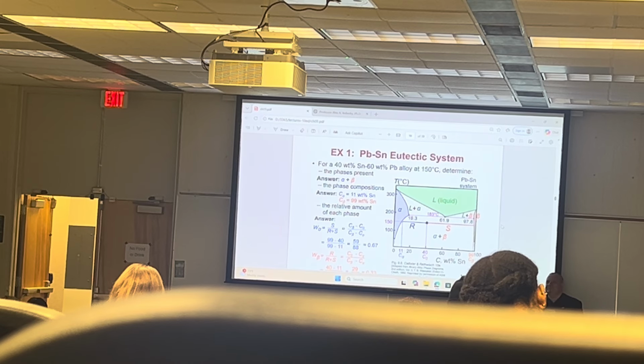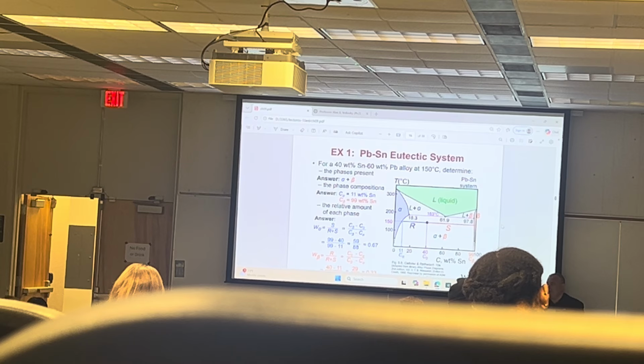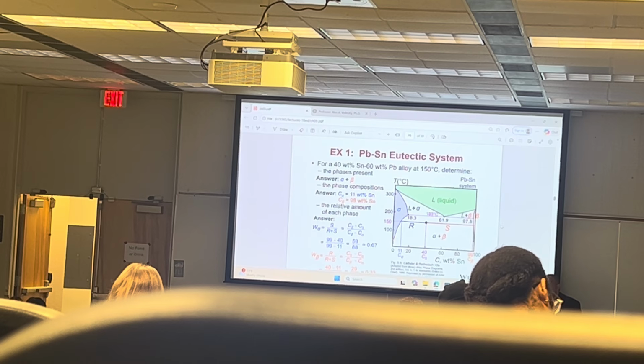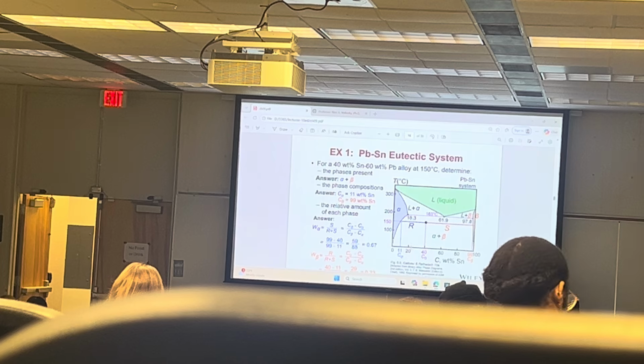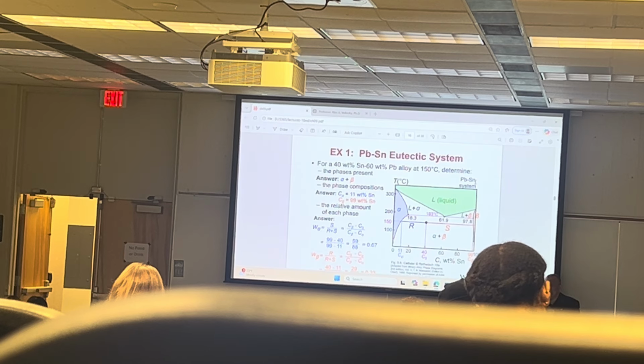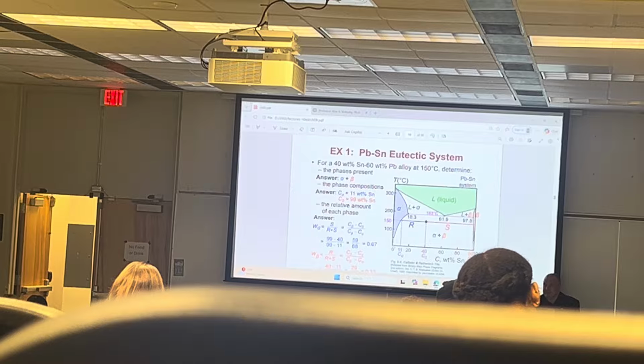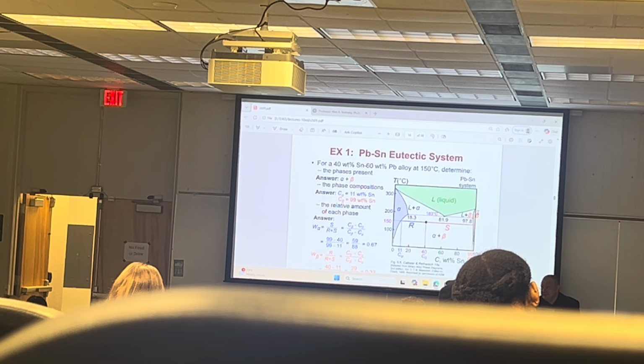I will show you another one. And the reason you have your cell phone in your hands and the reason you're carrying that laptop is because of this phase diagram. Okay, this is tin-lead, which is solder that's used to attach all of those components, all those chips on the printed circuit board, which is made out of plastic. And let's have a look. So this is lead-tin, and this is percent tin. So here it's 100% lead, and here's 100% tin.